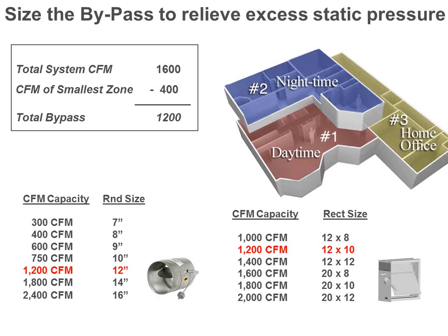Setting the bypass is super easy. This is showing you an older style bypass with a counterweight. There are also ones that are spring-loaded, and there's the new Honeywell one, which is really nice. You should check that out if you haven't already seen it. But in either case, it's the same kind of setup. You open up all the dampers, and then you set the bypass damper so it's just barely closed. In the case of this counterweight one, you keep moving the weight on the rod until the damper is shut, but just barely shut. Like if you had one more turn of it, it would open up a little bit. So you set it so it's barely shut when all the dampers are open.